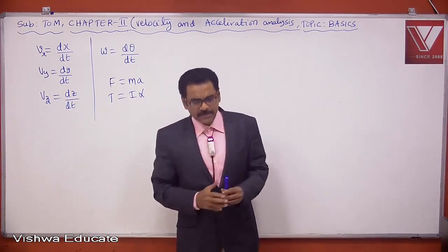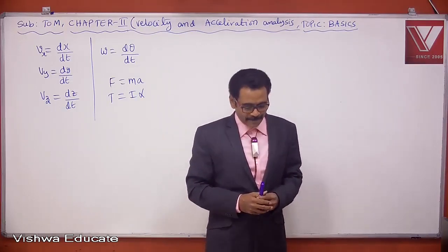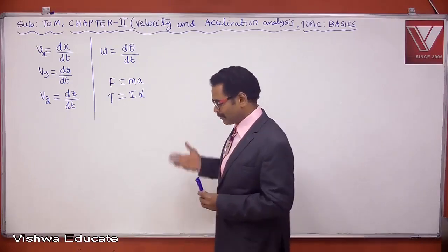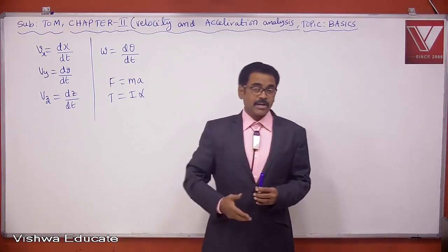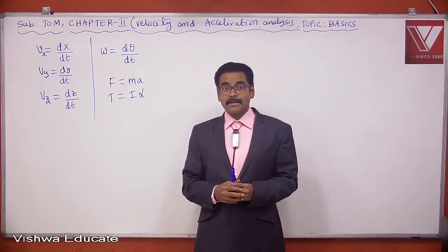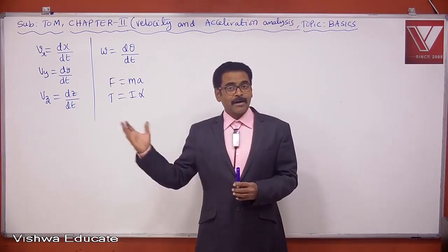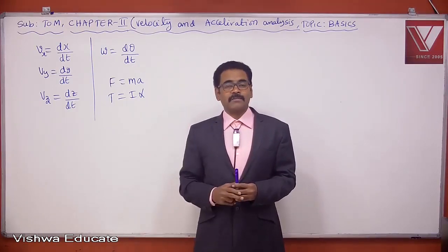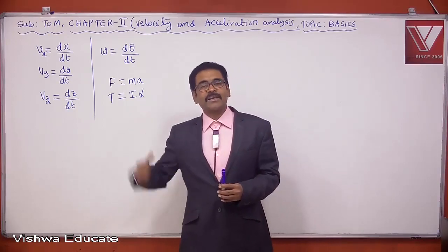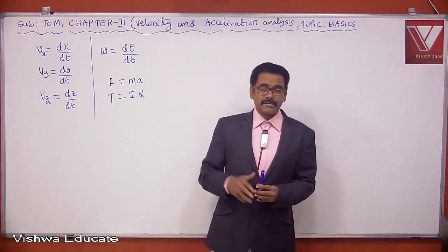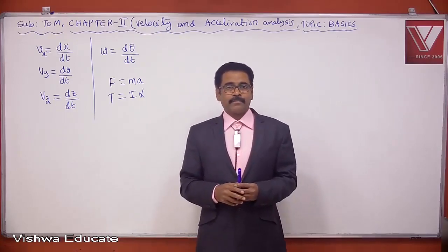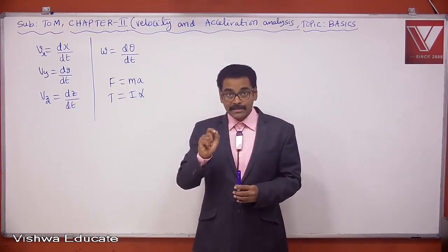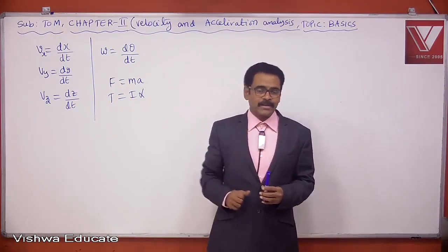For performing vibrational analysis, first I need to perform force analysis. First I should know the forces carried by links and the turning moments carried by links. Then I can understand whether all forces and all turning moments are balanced or not. If anything is not balanced, definitely vibration will start. Vibration comes primarily because of unbalanced force and unbalanced couple. But what is the starting point for all these things? The starting point is velocity analysis. Never forget it.